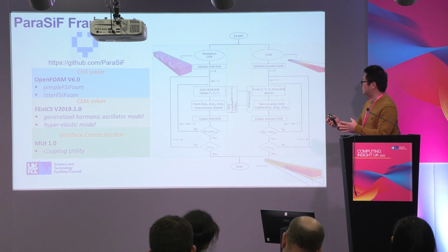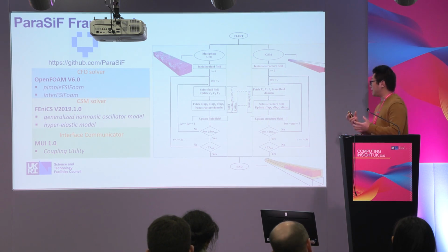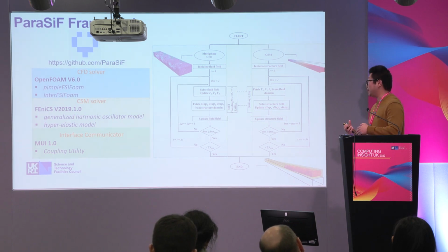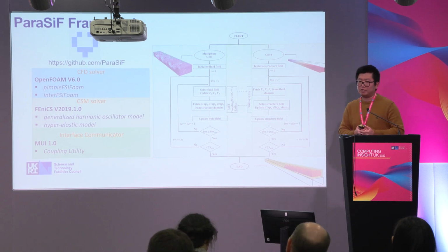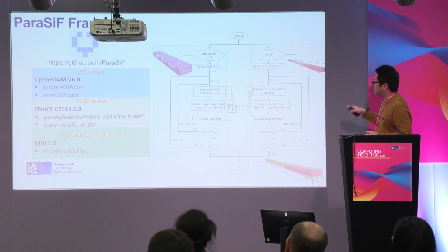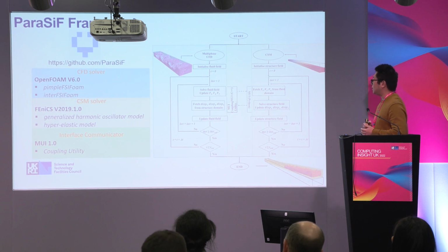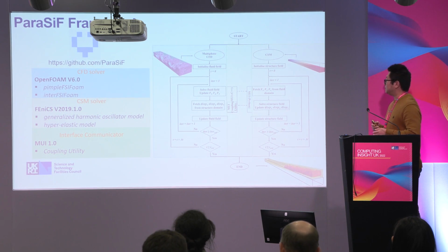It pushes the forces to the structure solver. Then the structure solver receives the forces, updates the deformation, predicts the displacement, and pushes it back to the fluid solver. A number of such sub-iterations are carried out inside one time step, and a number of time steps are carried out to simulate the whole time history of the case.